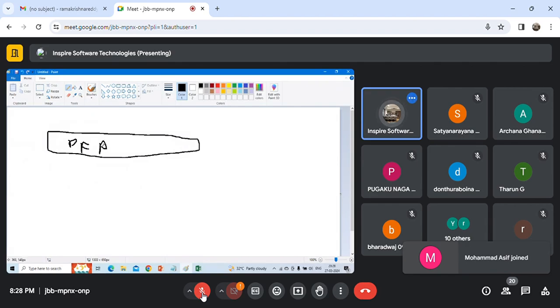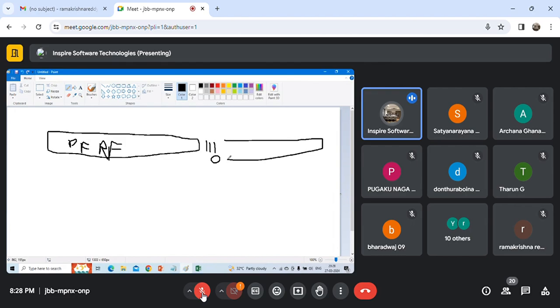After that, on the bus, every node should see three recessive bits. Let's say one receiver sees 0 in place of 1. At that time, that receiver will send, okay, I saw 0 in the interframe space, so I'm sending the overload frame. Somebody is using this bus, please take care. To inform that, the overload frame will be sent.